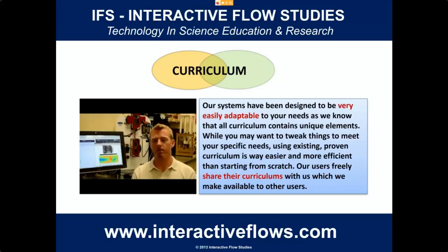Rapid prototyping plays a critical role in our curriculum, and it interfaces quite well with the Flow Coach and HemoFlow systems because we can reconstruct geometries from any patient data set from CT or MRI or even angio. And using those data, we can then rapid prototype a blood vessel model, recast transparent material around that, and then plug that material directly into our Flow Coach system.